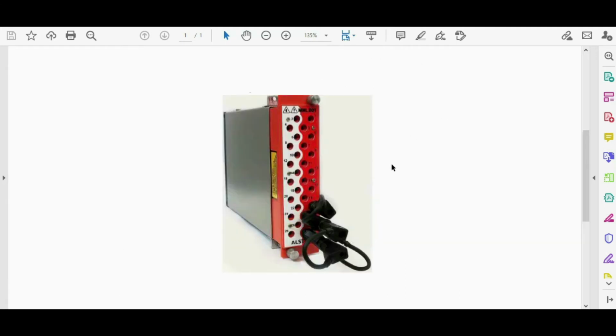Alright, let me show you the figure of the test handle and test block. The orange figure is the test handle. It is inserted into the test block and it's ready for the commissioner to test the relay. Now the commissioner can make a connection between the test device and the orange figure, I mean the test plug, and then he can increase the current and see the result of the protection function and time of the binary outputs.